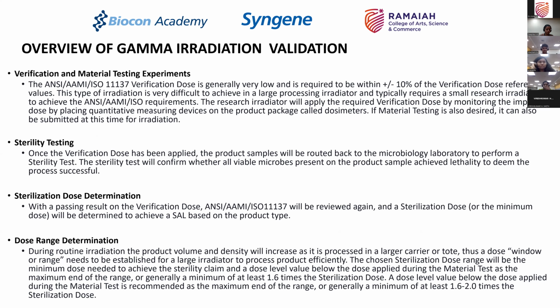both doing it higher than a certain dose rate and doing it lower than a certain dose rate will have a contradicting or a detrimental effect on the product. If you do a low dosage, you will not achieve sterility. If you do it higher, then you might deteriorate the product, or you might decrease the shelf life of the product, or both. In such a situation, you have to fix a window.